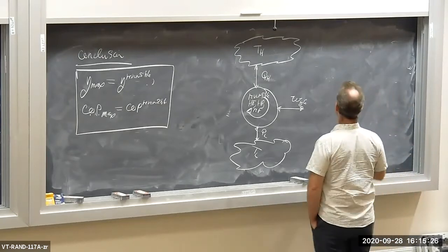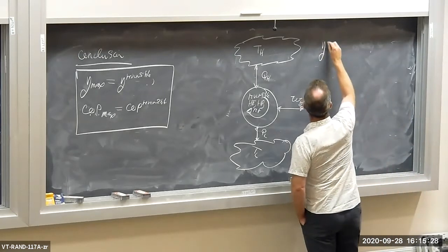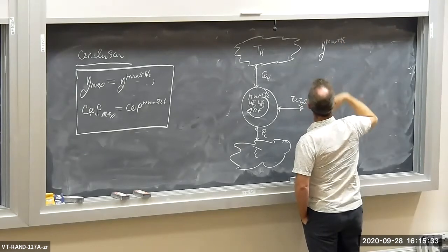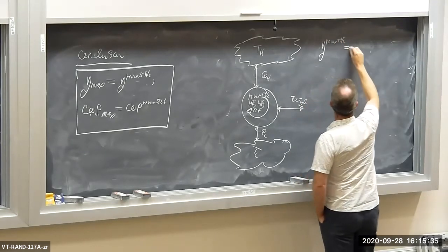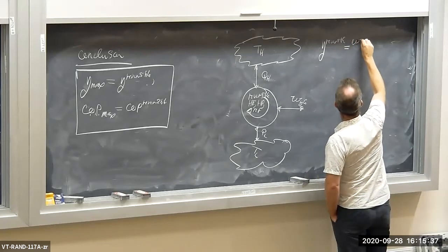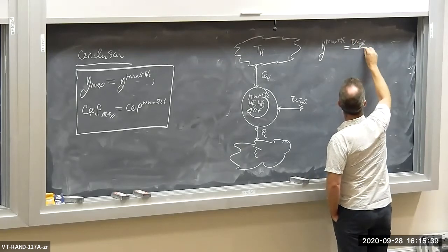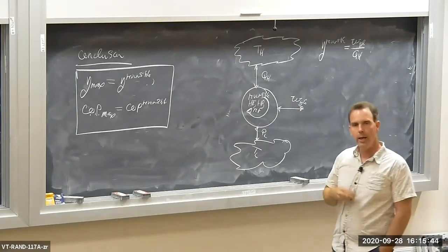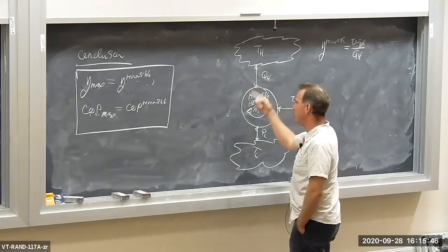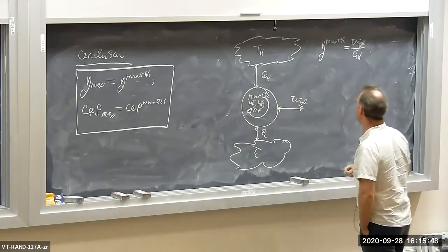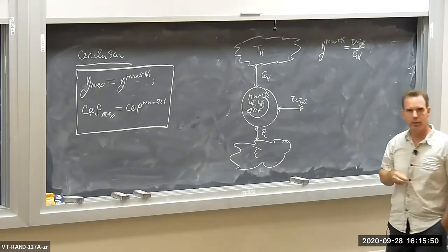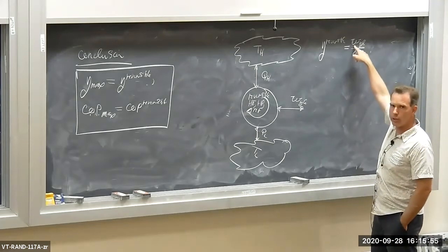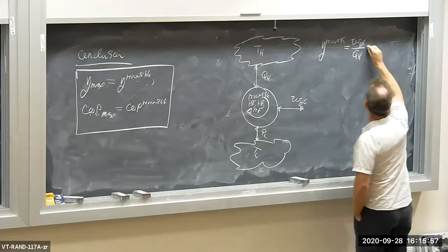Let's see here the efficiency for this reversible heat engine. That's going to be equal to the cycle work over QH. If you apply the energy balance to the reversible device over the cycle, you'll find that the cycle work, W cycle, is QH minus QL.